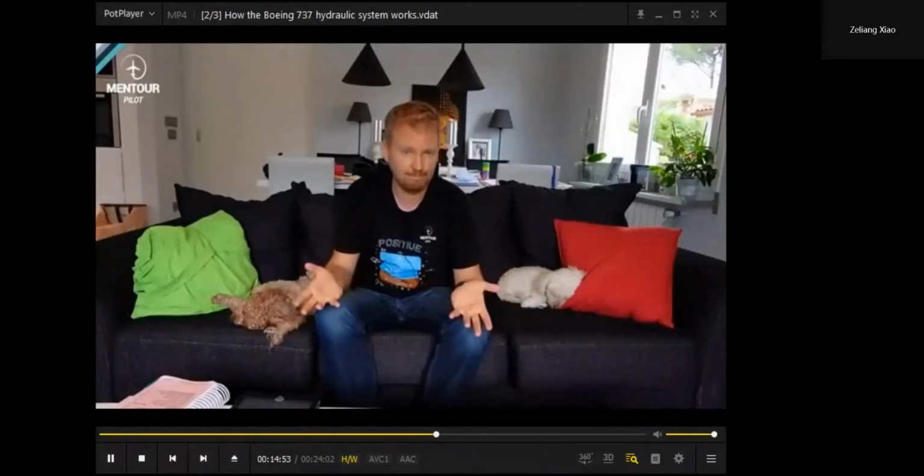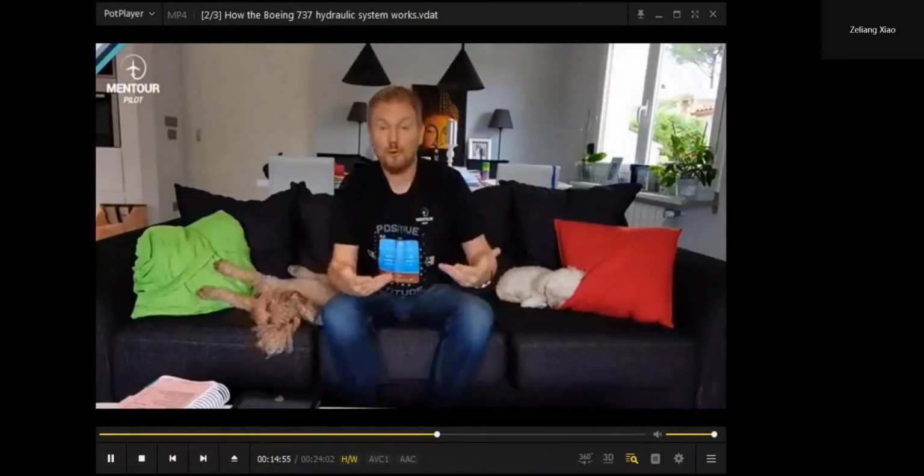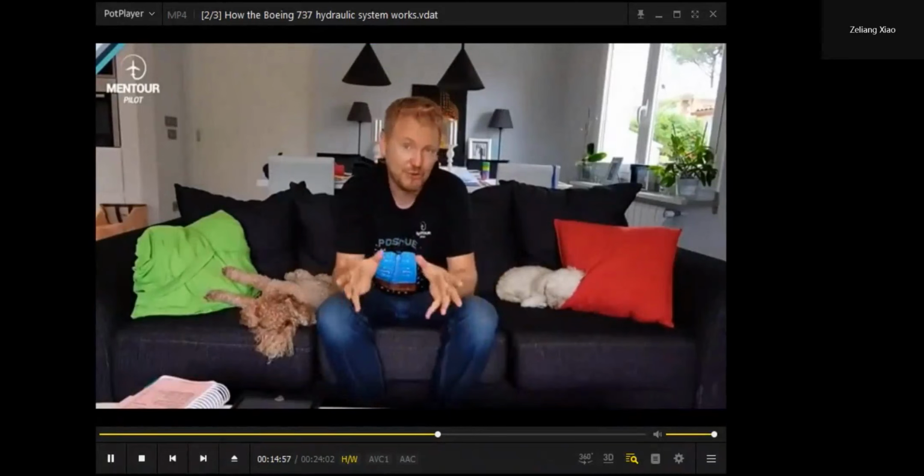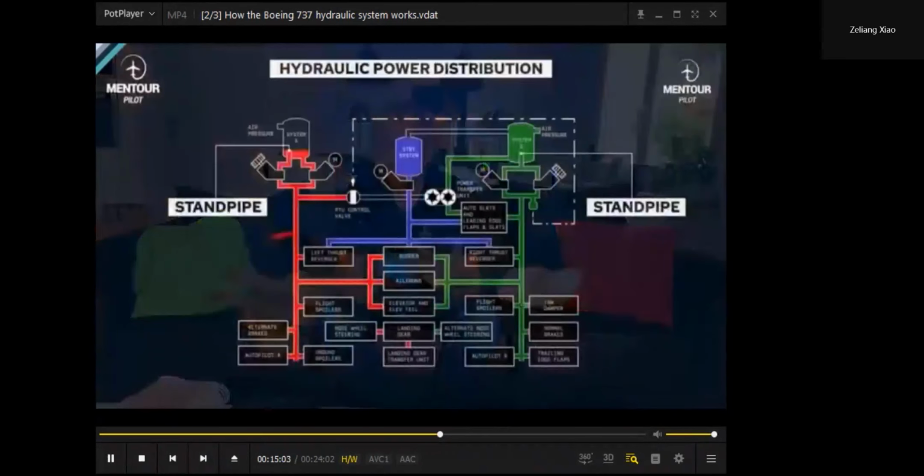All right. So what about failures then? Well, we've kind of touched on it a little bit already, but I just want to highlight a few things. If you have a leak in a system component in either of the systems that is downstream of the pumps, you are likely going to lose that hydraulic system. But as I've indicated already, it's not that big of a deal because all of the really important functions are being picked up by the other system, for example, how to control the aircraft, or by the standby hydraulic system.